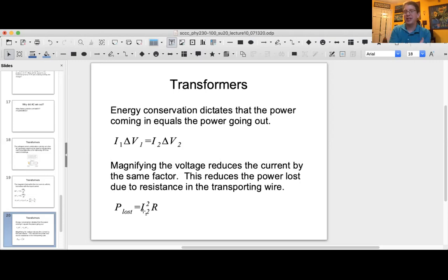And so the step-up transformer gives you a high voltage, low current, and then when you get into a residential area, you have a step-down transformer that reduces the voltage and increases the current. If you look outside at the power lines and you see a bucket with a wire heading towards your house, that's a step-down transformer. That's converting the voltage-current combination to something that is suitable for your house.